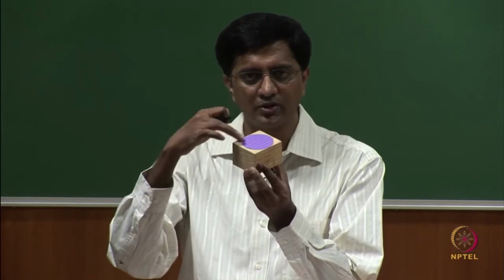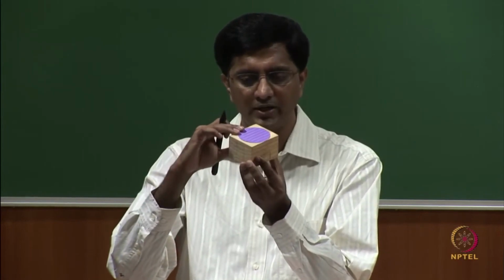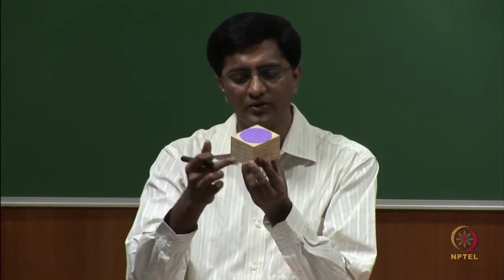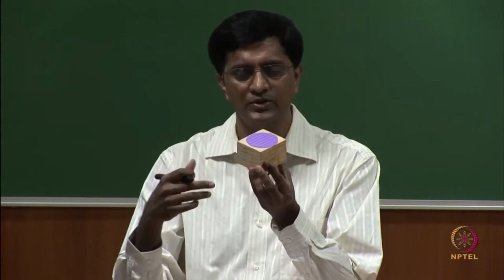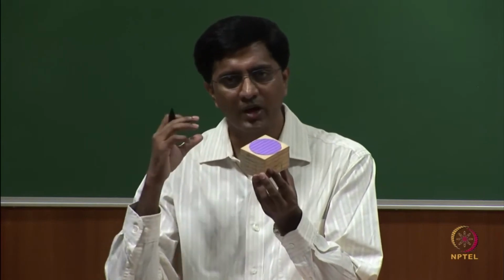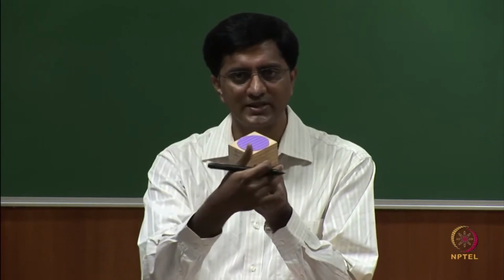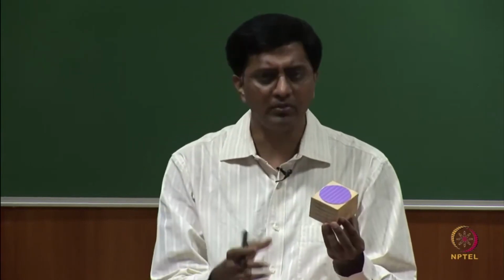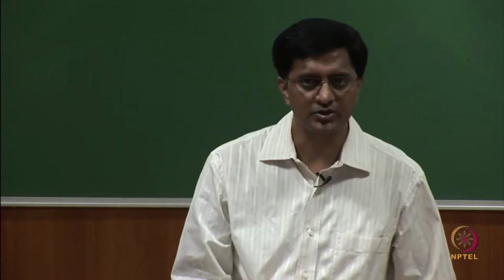If you focus on the top face, by tilting you will see less and less of this top face, but more and more of the front view and the side view. So, you are emphasizing more the front view and the side view and less the top view, but it all depends on the choice of the angle.